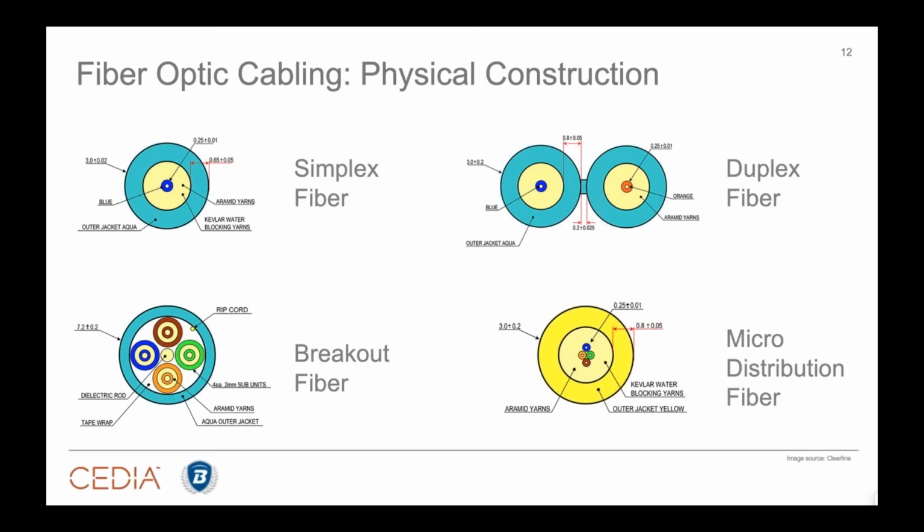Now, here's the thing. You can buy extenders, HDMI extenders, that use one strand of fiber, simplex fiber. We make them at TechLogix. Other manufacturers make them. A lot of people think fiber does not send signals bidirectionally. It only goes in one direction. And while, yes, it's common that you always need two strands, you can have bidirectional communication. We just shoot our waves at different frequencies, different wavelengths. And that's why simplex will send HDMI. You have a handshake, you have bidirectional communication.